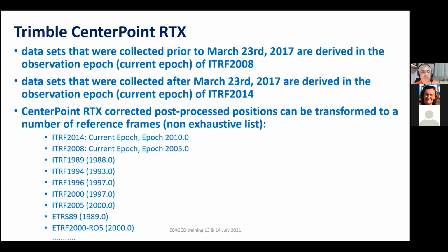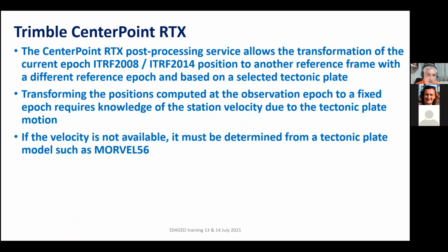Of course, there is a number of other reference frames, which is what is interesting for us in Europe. It is the ETRS 89 at epoch 1989.0 and ETRF 2000 release 05 at the reference epoch 2000.0.